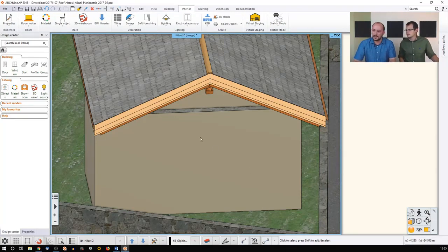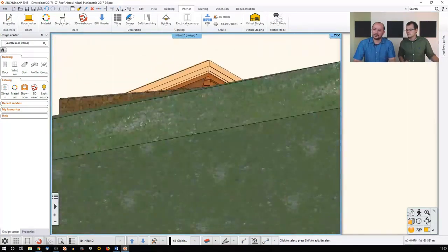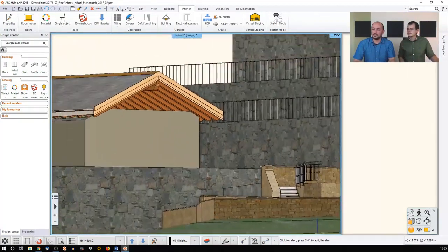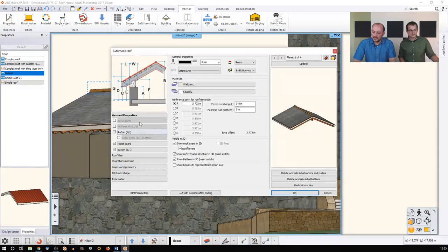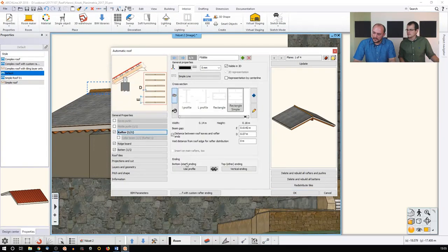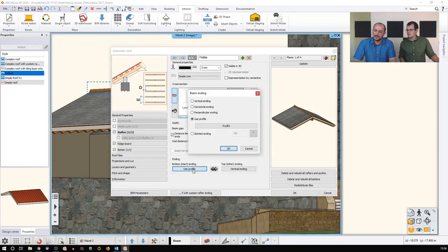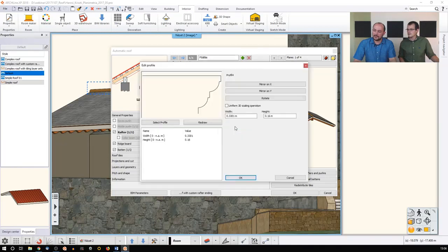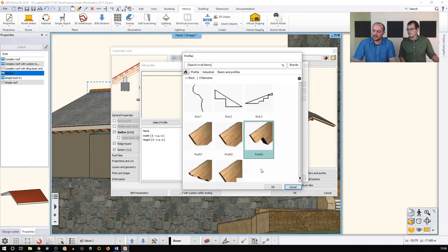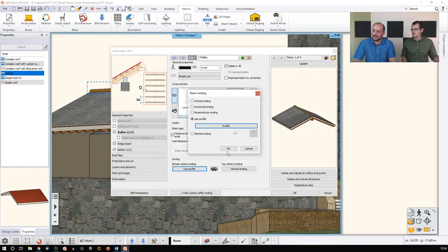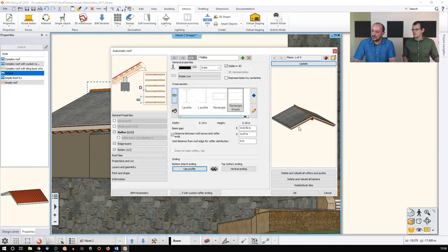The rafter endings are something that is controlled within the software, within the roof structure itself. So if I go into the details, I will find the rafter, and there is the ending, and there is the user profile. This is something that I have created or selected. This is different from the cross-section profile. If I click here, I can find that there is something called profile 4, and it looks like this. Actually, the software comes with built-in ending profiles. I can select this, this, or this. And when I do that, I click OK, and the software will update that for me.